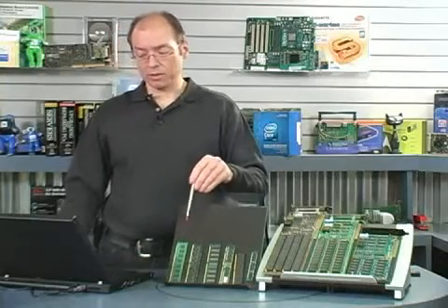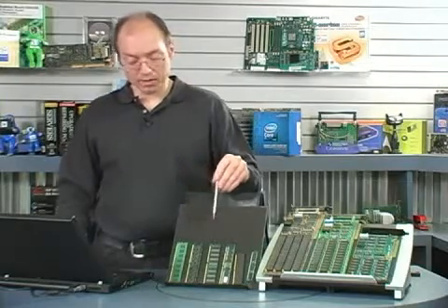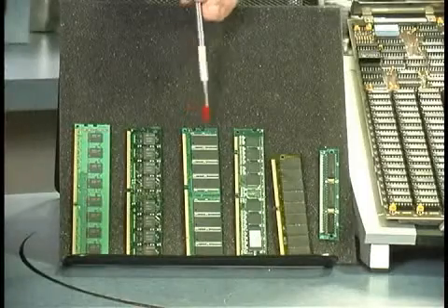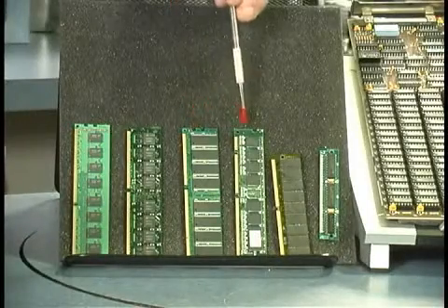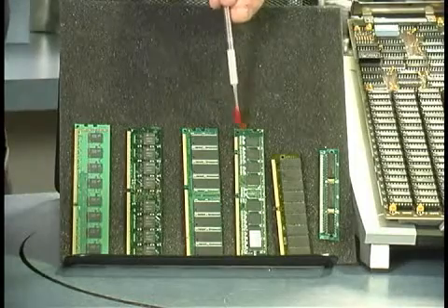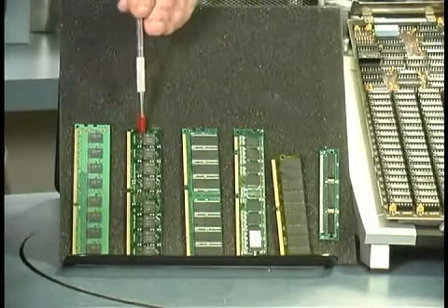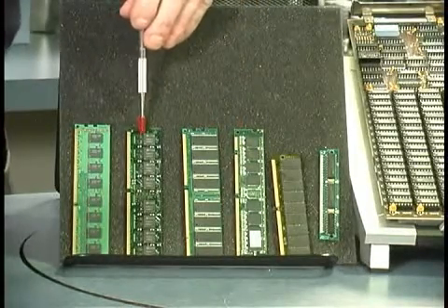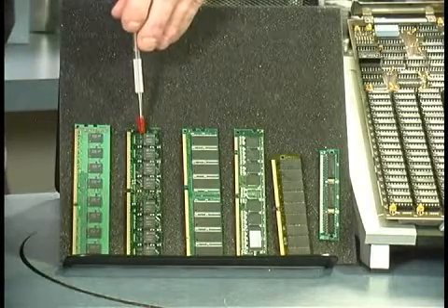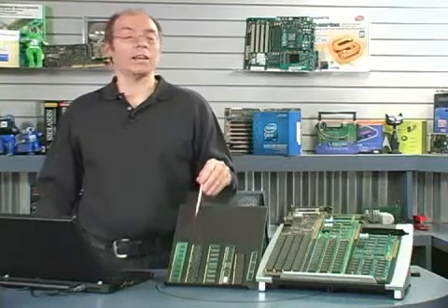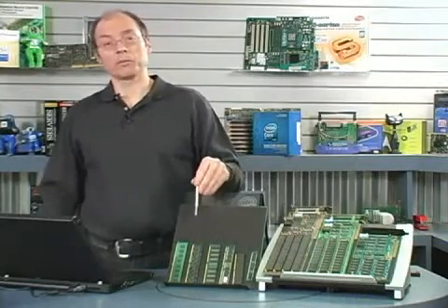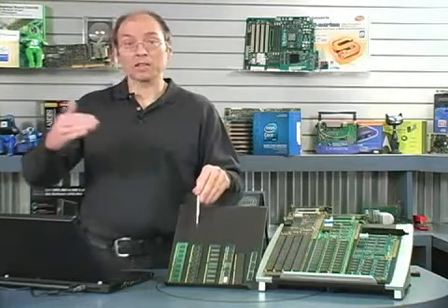Now let's take a look at a little bit how this technology works. We mentioned that the double data rate ran at twice the data rate of the single data rate modules. Now DDR2 is not like a quadruple data rate. What they did there was they added extra signal pins in order to improve signal integrity, so the clock could go higher.